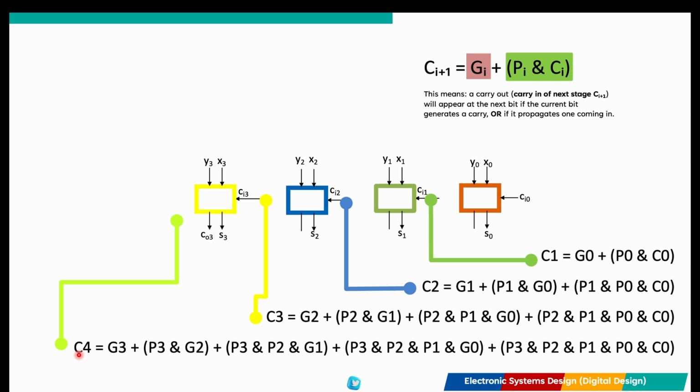In short, the ripple carry adder is like a line of people passing a bucket of water. The carry look-ahead adder is like a supervisor looking at the whole line and telling the last person to get ready before the first bucket even moves. As we move into a more complex design on the DE10-Lite later, understanding this trade-off between gate area and timing performance is what separates a student from an engineer.